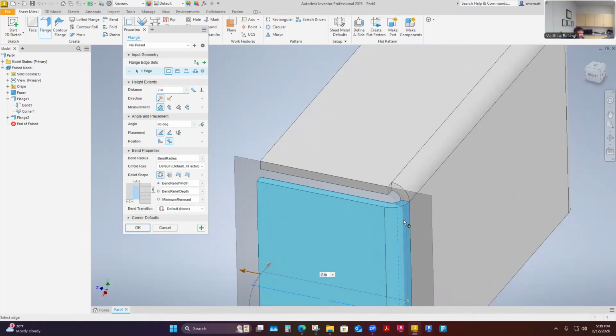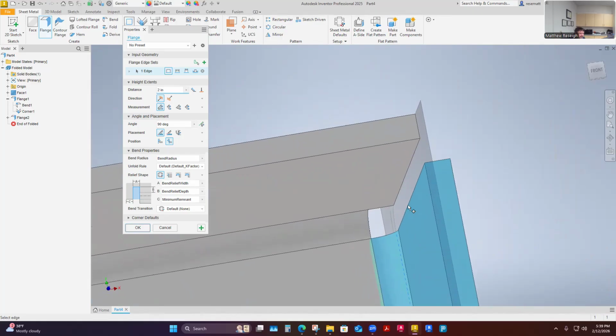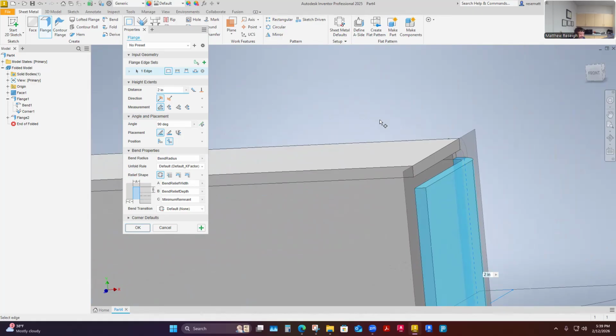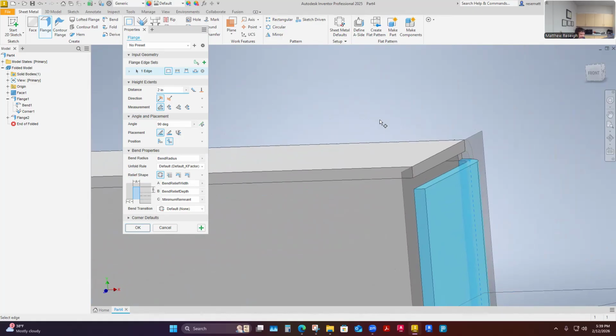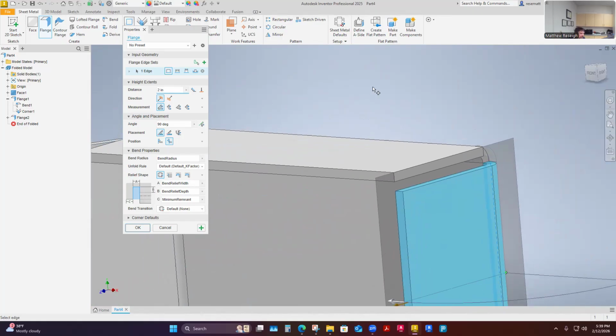That all I have to do is put some material in and fill up, there's a nice natural resting place for a weld to sit. But when I create this gap, that's not ideal, especially on thin sheet metal parts. Gaps in thicker parts are okay and designed that way. Gaps in sheet metal are generally not wanted by a welder.